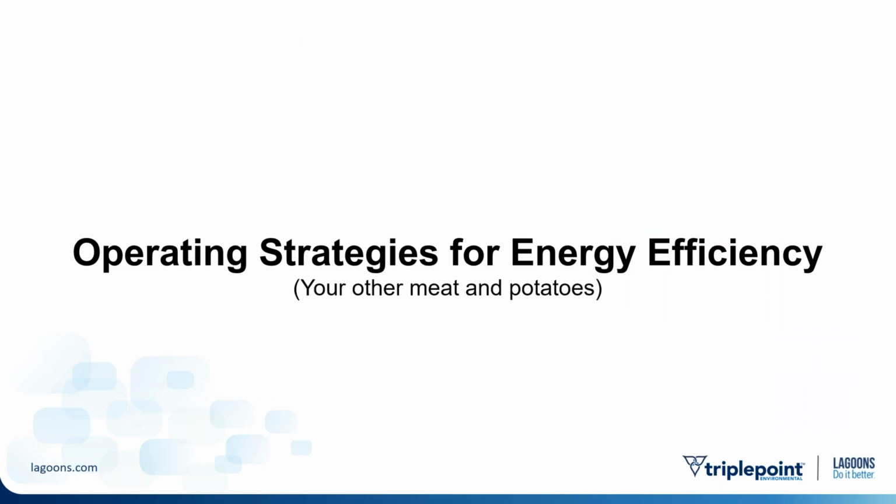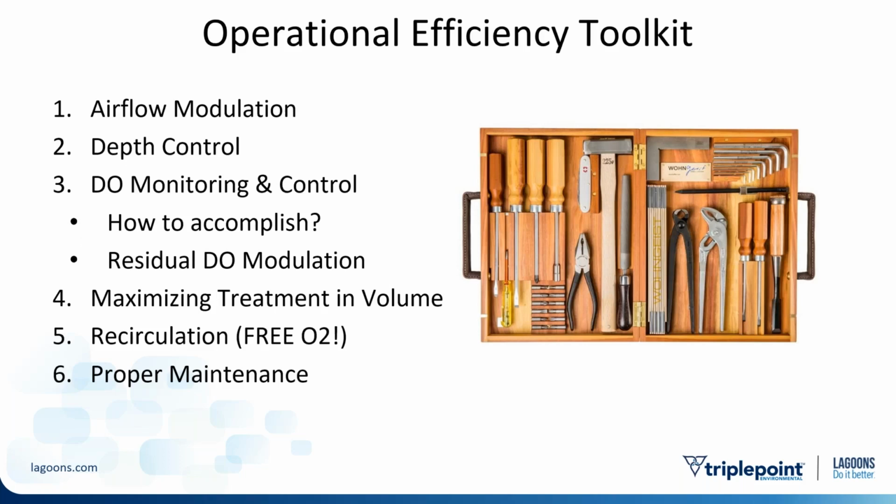And on cue, operating strategies for energy efficiency. So these are some toolkit items that an operator has to change the energy efficiency of their lagoon system. First is modulating airflow. That's a really big one. Depth control is a big one. DO monitoring and control. How do we accomplish this? And I have an opinion on that I'll share with you. Making sure we're maximizing the treatment volume of the lagoon, and recirculation, actually, and also proper maintenance.